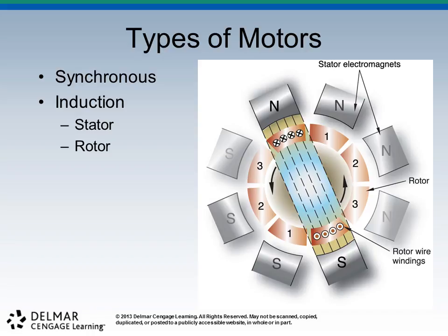We've got a sealed piece of glass that goes around here. It's sealed to maintain a vacuum for other reasons, which we'll get to. But we need some way to mechanically make activity occur inside the tube, and so a magnetic field will reach right through that glass, doesn't even know it's there, and will induce this rotor to turn when we activate the stator. It's really a simple principle. And if you've ever looked at your car alternator or at a fan turning, or we've got a fan in the lab too, it's essentially the same technology that's making this spin happen.